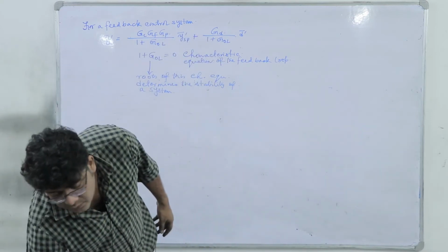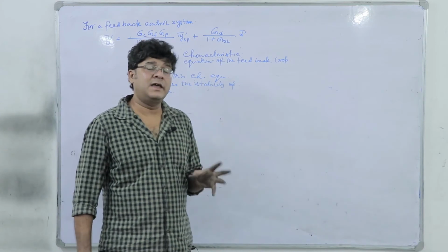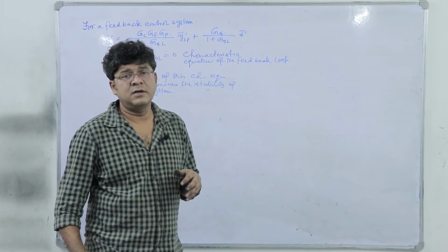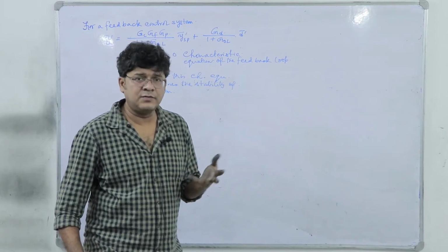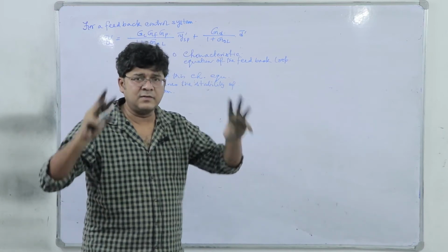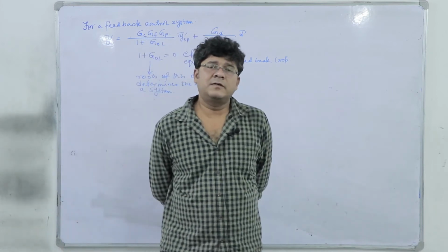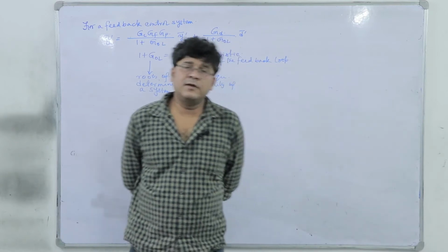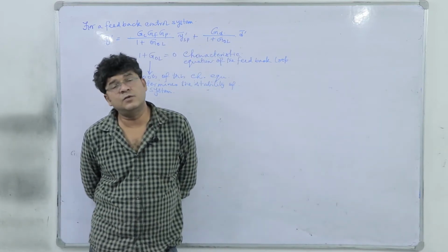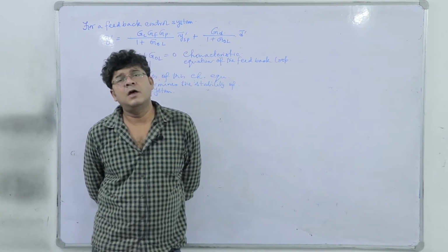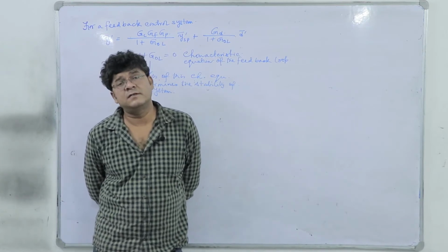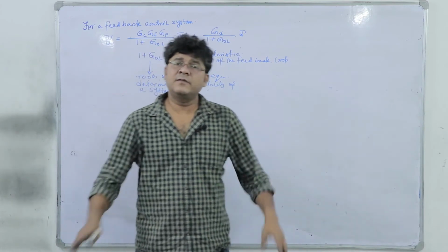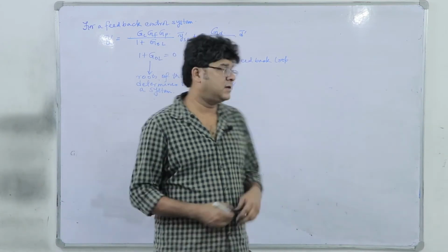So, we have to keep in mind that we don't want the exact values of the roots of this characteristic equation, right? Rather, we should call them roots, not poles. It's not exactly the transfer function of a system, but rather the transfer function of the entire feedback loop, right? For the roots of the characteristic equation, we don't have to solve. We only have to know the sign of the real part of the respective roots, right? And from there we can conclude about the stability.